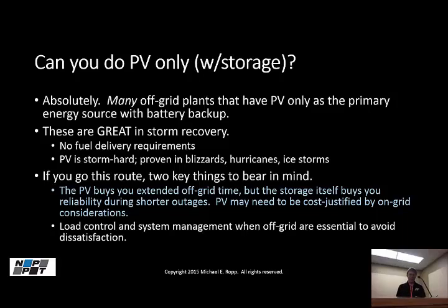Remember that what the PV does is it buys you that extended off-grid time. The storage is what buys you the reliability during the shorter outages. So actually, lots of times, the storage by itself is all they really need. They don't need the PV if your average outage duration is sufficiently short. But again, the real key is you've got to have a lot of load controls.